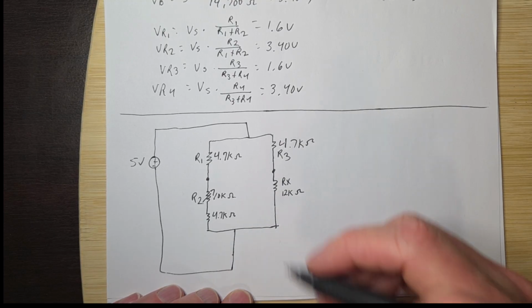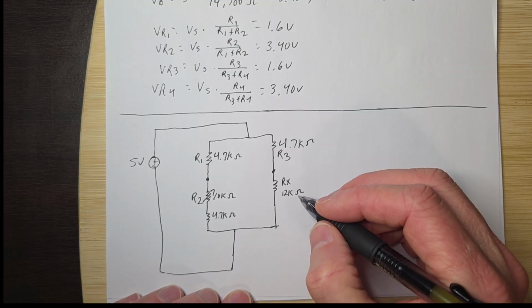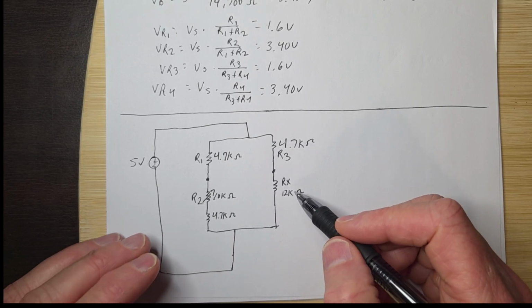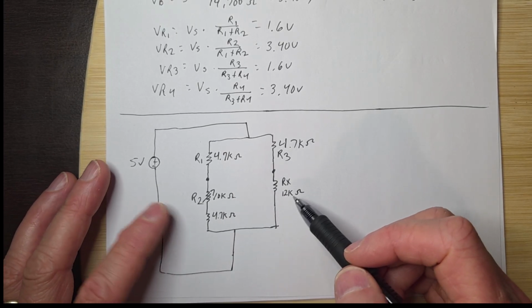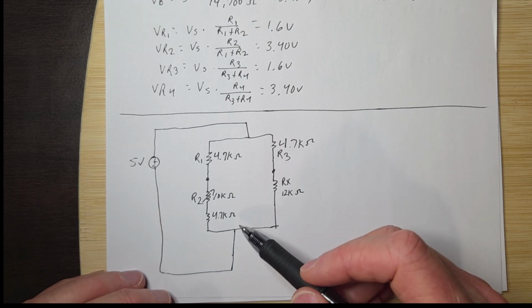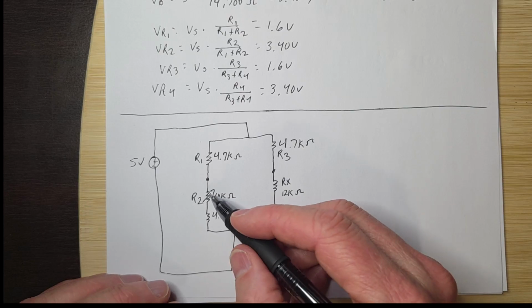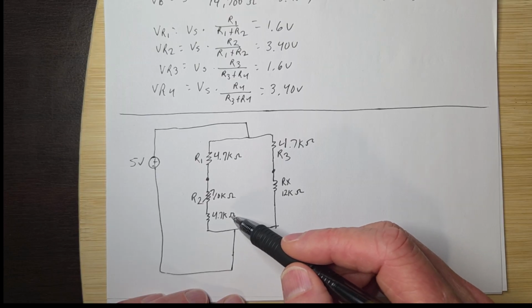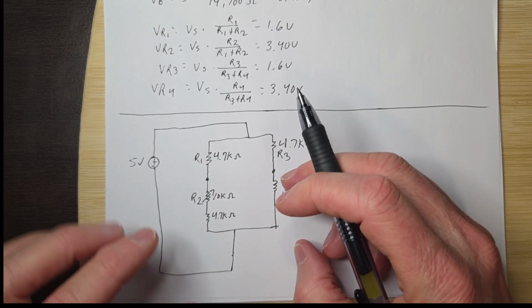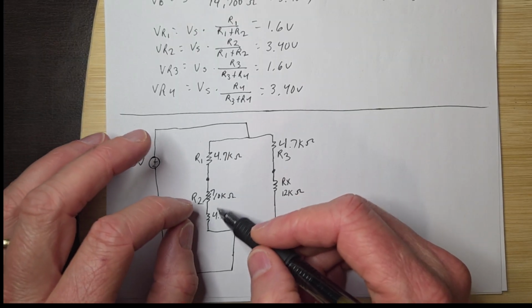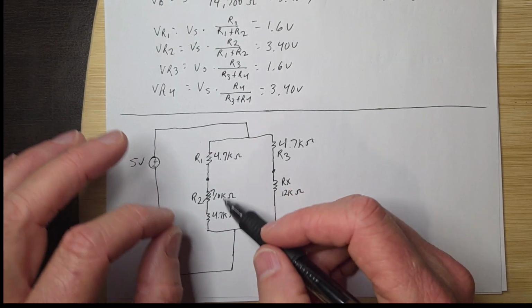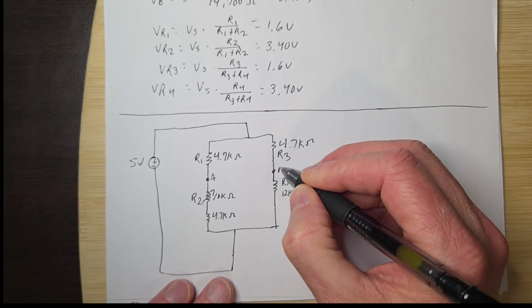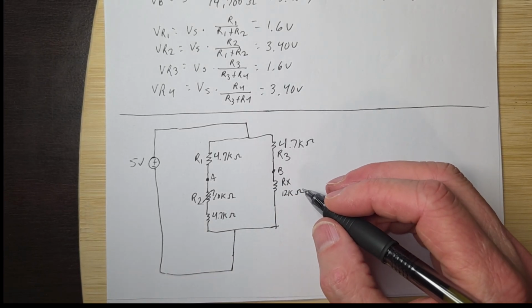And luckily, this thermistor's resistance goes down the hotter it gets. So I had to get up around 12K or whatever it was initially to get it to balance out. This way, that provides me enough resistance to do that. That's why it looks a little weird. But just pretend this is one resistor that's 14.7K ohms, and it's adjustable, and we can adjust it and get it to balance out. It's just that I had too small of a potentiometer, and of course this is A and B, and I'll show you that in the lab in a minute.